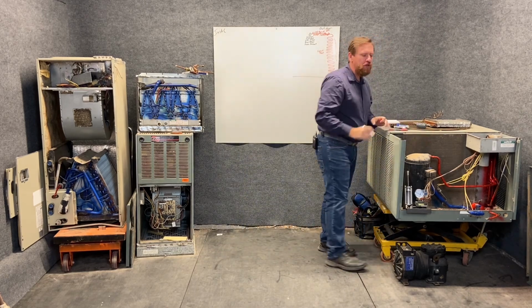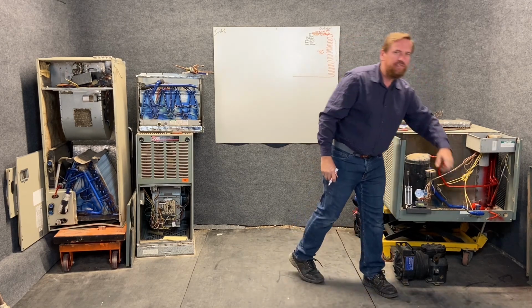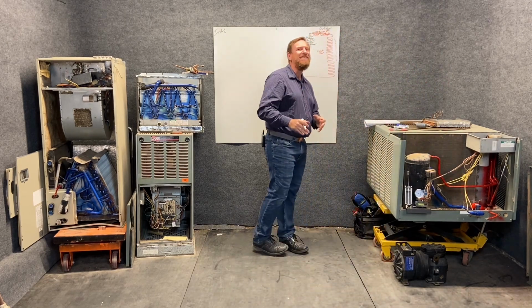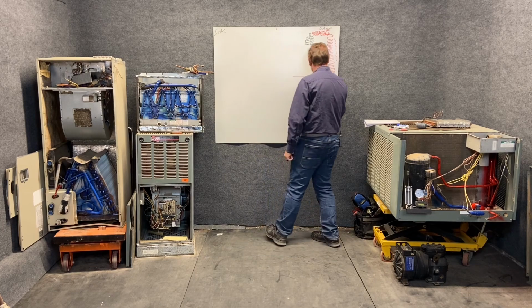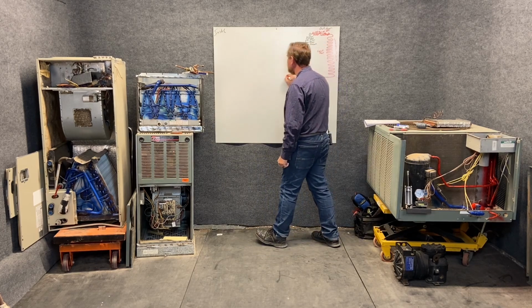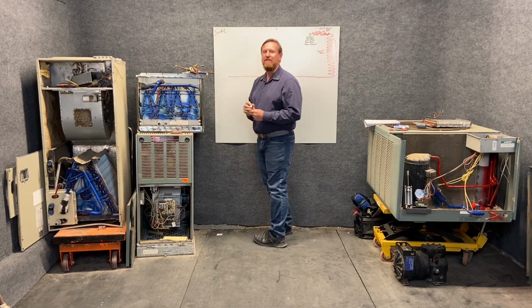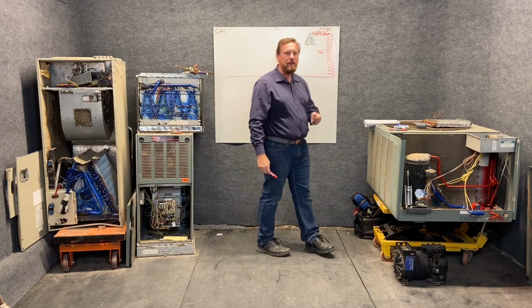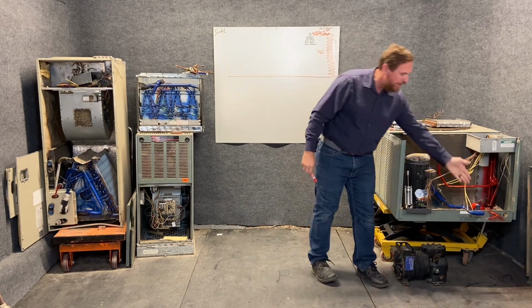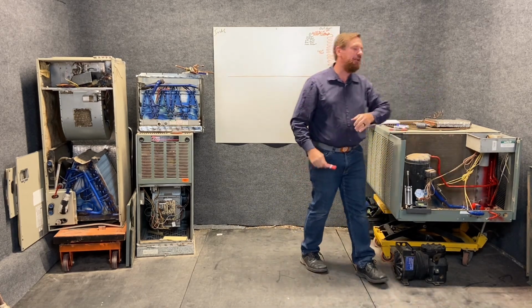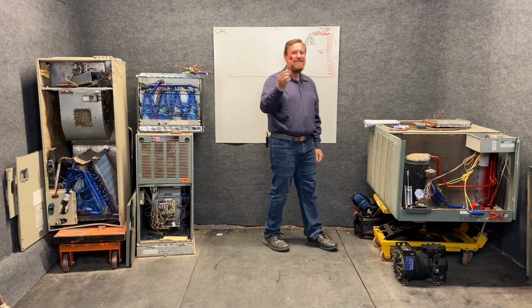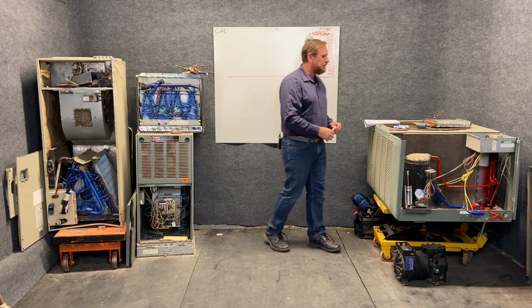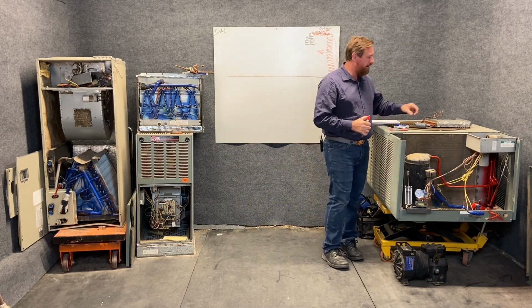So now that we've pictured this condensing coil, we're also now going to picture our liquid line. The liquid line is leaving the condensing coil. That liquid line is going to connect the outdoor condensing unit to the indoor unit, our metering device. But that liquid line, the small line, it's more like a 3/8 line. If you look at the units, there's a bigger one and a smaller one. It's going to be the smaller line. It's still going to be red, still going to be high pressure. This is where we're going to use our high pressure gauge.